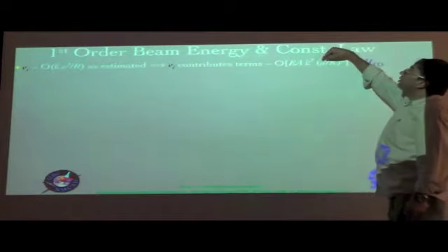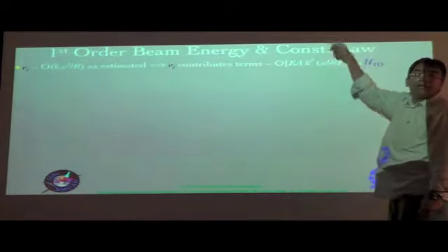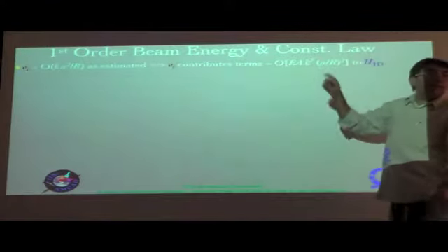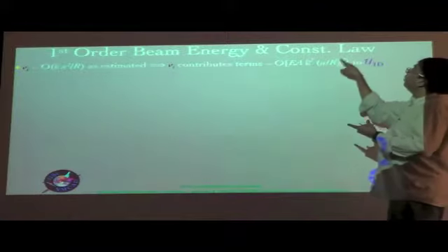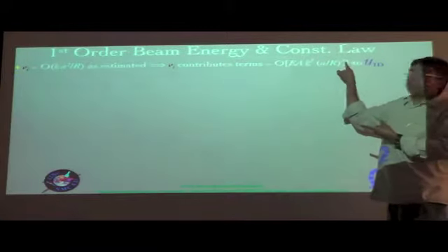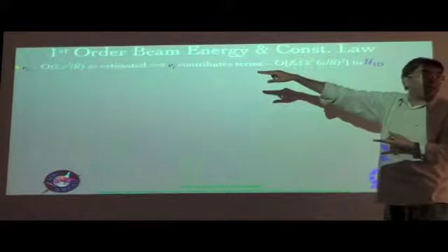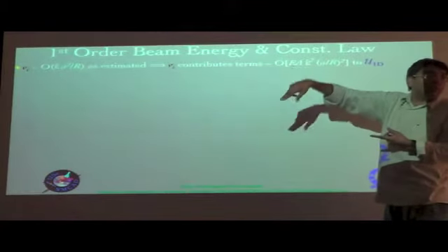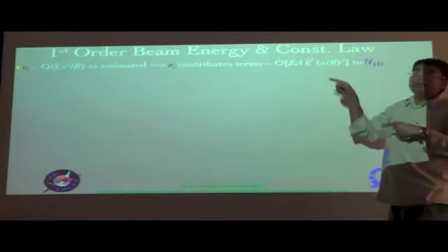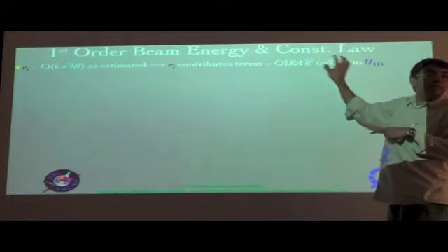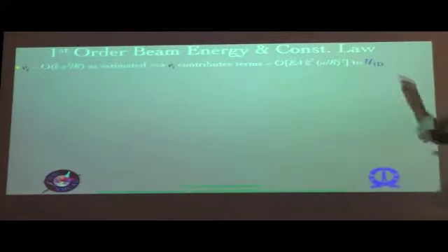Now, because in the strain you are taking one term A by R, and you know that the strain energy is quadratic in the strains, it becomes the square of that, because you have a perturbation A by R in the displacements, and therefore the strains. Because the energy is quadratic, you would have A by R squared as the correction to U1D.